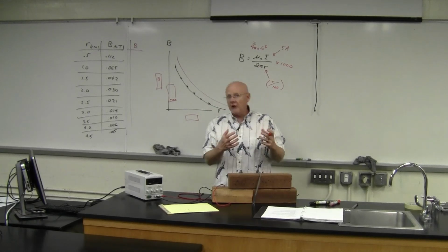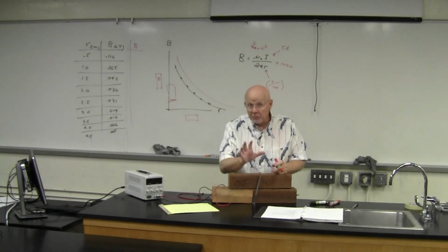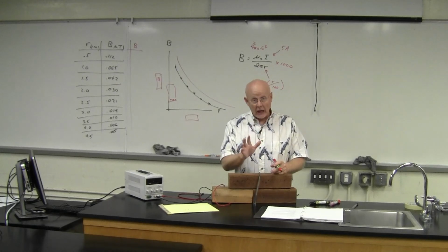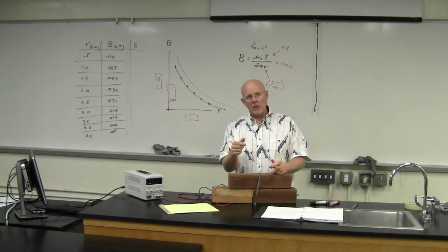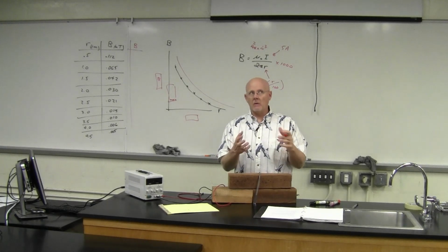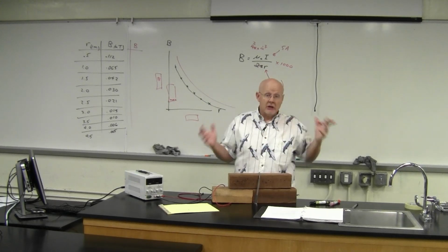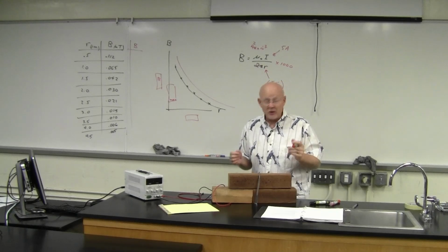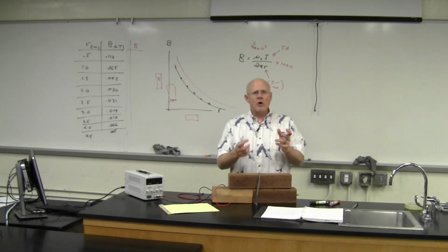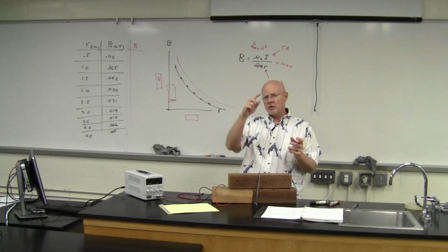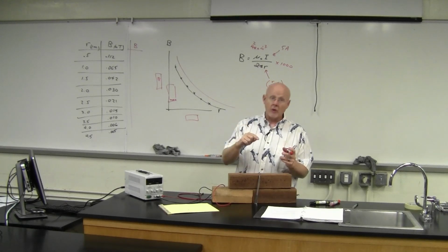So by default, Graphical Analysis only plots one at a time, and so if you click on it and you change it to the other one, you might be going, wait, I can only get one or the other. But no, you can get both, and you can get an infinite number. Well, I'm sure there's a computer limit, but you can get a lot more than just one if you go to the More option. So click on it and don't select the column you just calculated, go to the More.